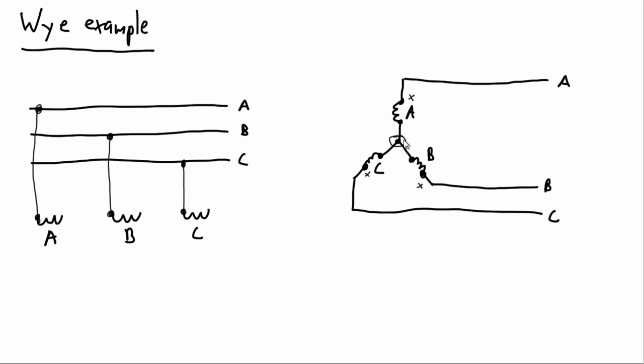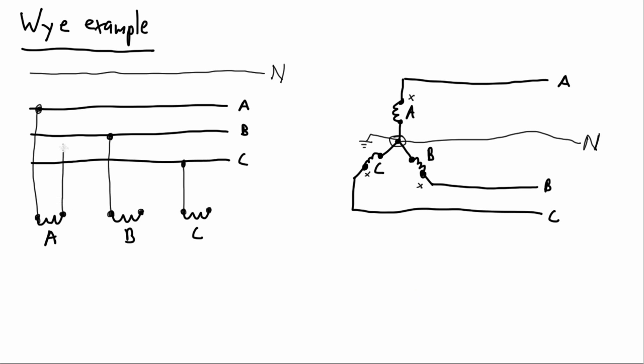One of the great strengths of the Y connection is the simplicity with which it can employ a neutral conductor. And that's what we're going to see. We're going to see now the neutral come into play. So let's draw our neutral line up here. So actually we have a 4th line, very different from the delta connection. We have now, instead of 3, we've got 4. That neutral now is established as the center connecting point in the Y, and we see that at that center point, it branches out into the 3 unique inductors. So it should be obvious visually seeing this that each of the inductors has to have a direct and immediate connection to the neutral. So very simply, we make that connection appear here. So now we have 6 total connections and 4 lines.